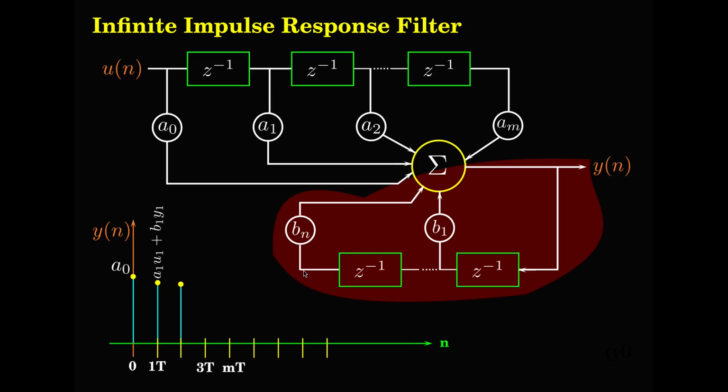The unit impulse would have shifted here and passes through A2. So you will have the unit impulse multiplied by A2 coming in here, plus one delay coming in here, two delays of the output coming in here, adding up, and then you get the output.